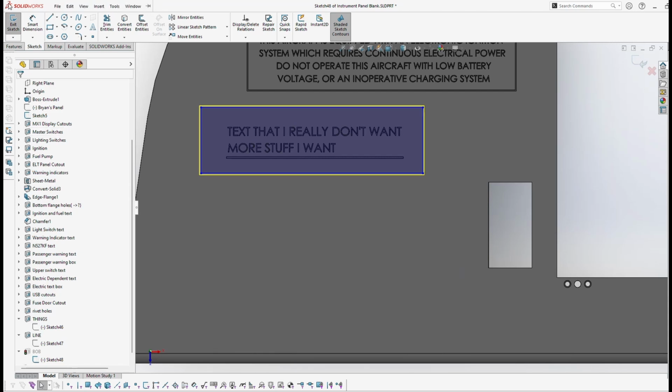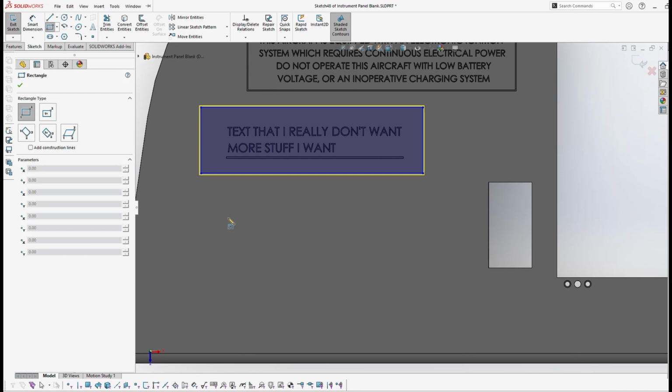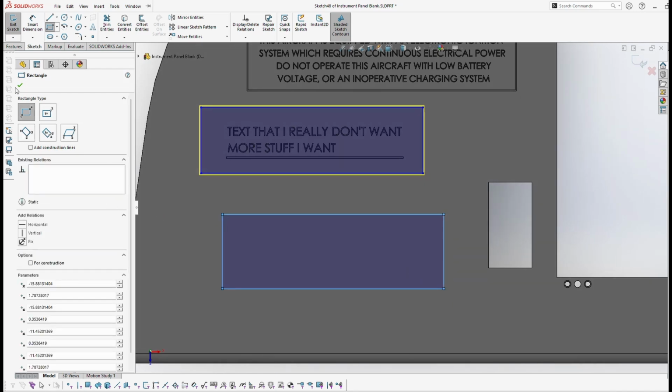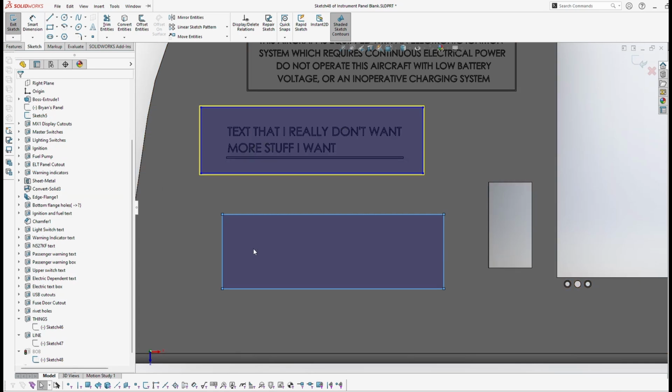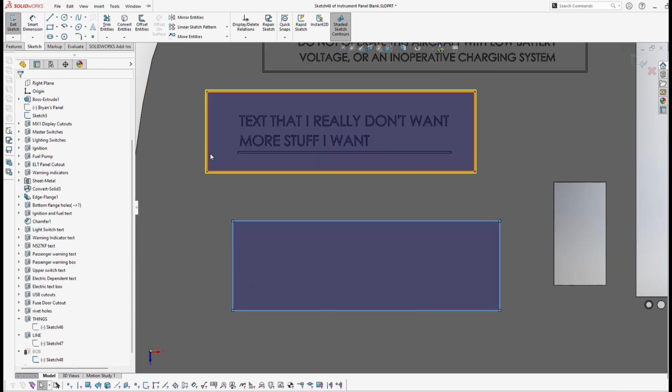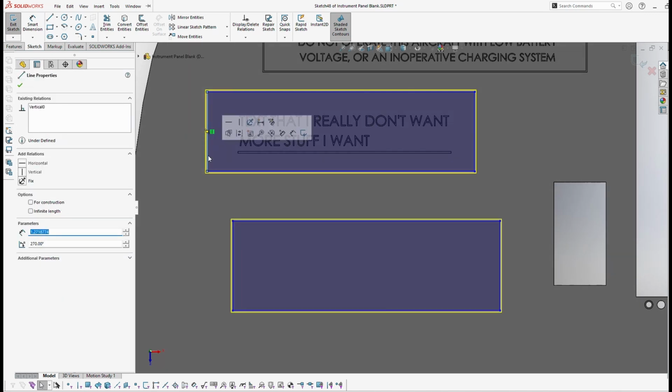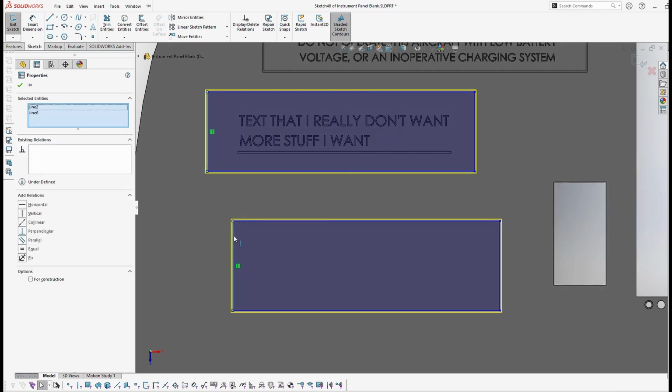All right. So I just backed out of that. I'm going to create this rectangle again. I'm going to intentionally mess this one up. And then I'm going to show you how to associate them so that everything is lined up smoothly. I'm just going to start over here on the left side by picking that line. I'm holding down Control, and I'm going to click this line.